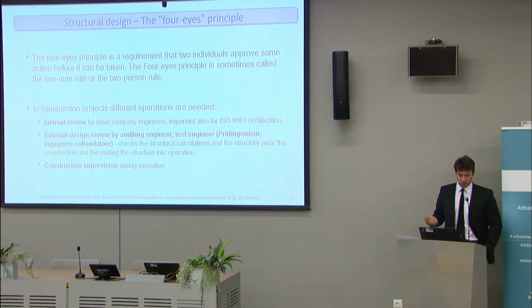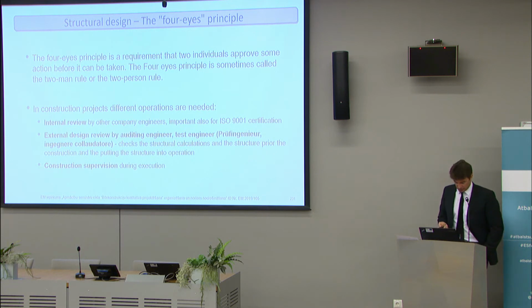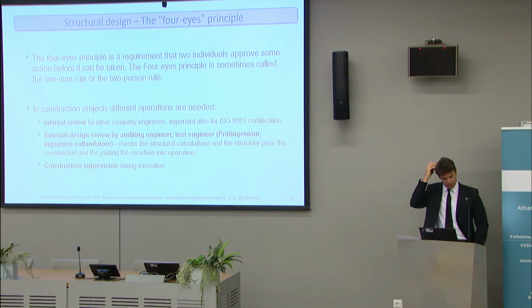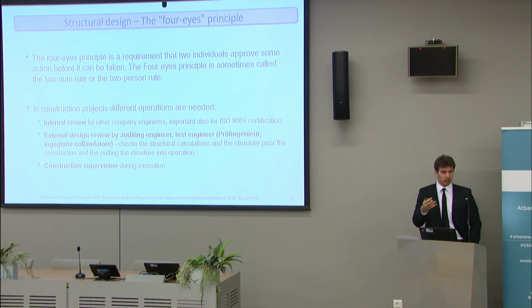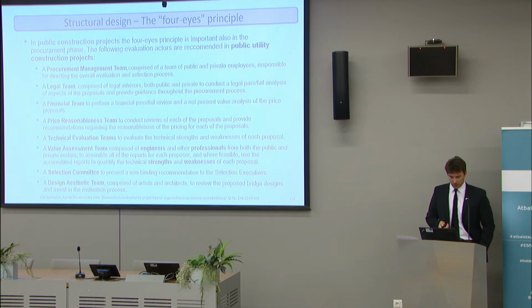And then we have construction supervision during execution, which is also very important for big projects. For example, they are very, very strict in this bridge project, where we are doing the project management right now. They independently control the direction of the borehole. They come to check all the materials. They also make tests on the anchors after they are installed, and we are going to see some pictures later.